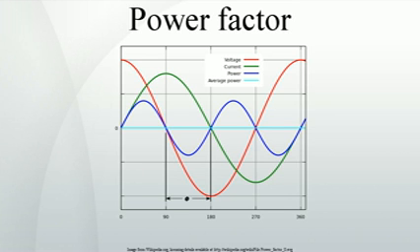Due to energy stored in the load and returned to the source, or due to a nonlinear load that distorts the wave shape of the current drawn from the source, the apparent power will be greater than the real power. A negative power factor occurs when the device which is normally the load generates power which then flows back towards the device which is normally considered the generator.